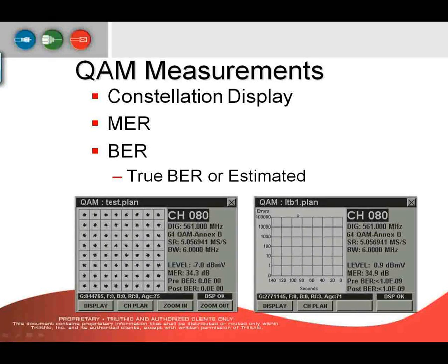Now, the transmitted values of the I and Q occupy only a few predetermined, widely separated states. A modulation protocol, a set of rules, prescribes the number of allowed states for each type of modulation. For example, in a 16 QAM, the I and Q signals can have only 4 allowable states for each. In 64 QAM, each can have 8. So you can kind of understand what that's referring to.